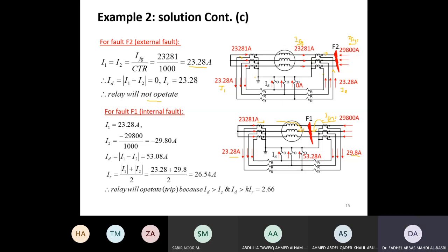Okay. So sorry, in the other direction. It should be leaving the dots, means leaving. This is leaving, this is entering. It should be in this direction, so this should be here. That's why it's just in this direction. Now, if you compare the two, this is in and this is out. So the differential current is 0.